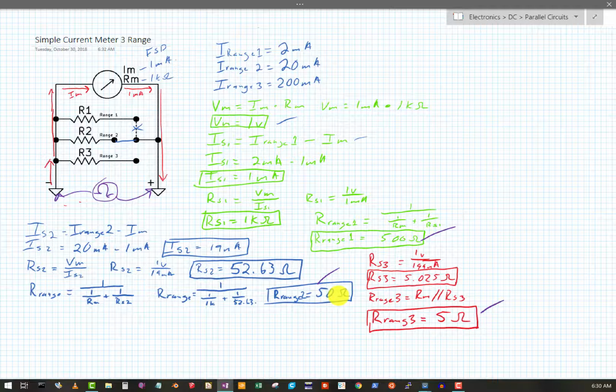What you can measure accurately is your full scale deflection voltage, which is 1 volt. You adjust for full scale deflection, and you should measure about 1 volt if everything is built properly. These predictions should be good, but to prove it, we can go into the lab and take measurements.